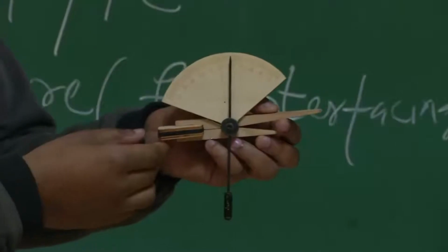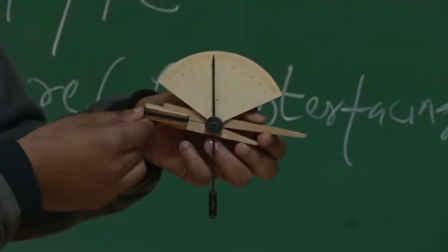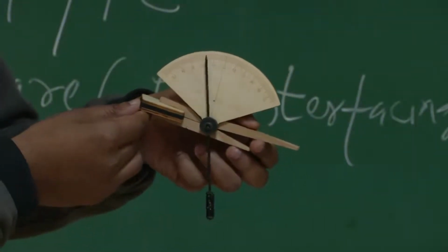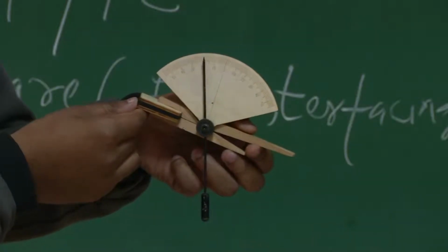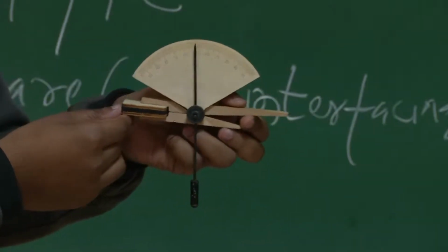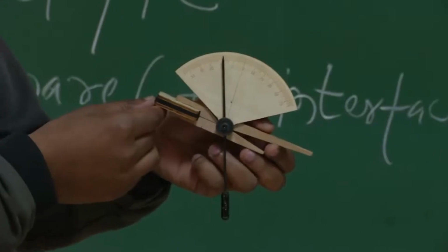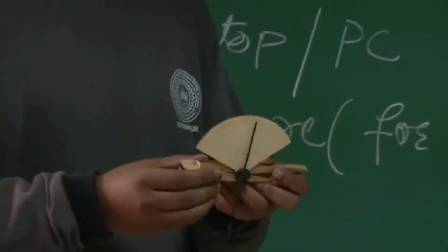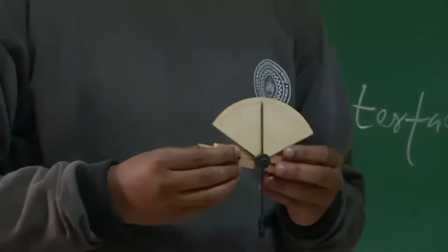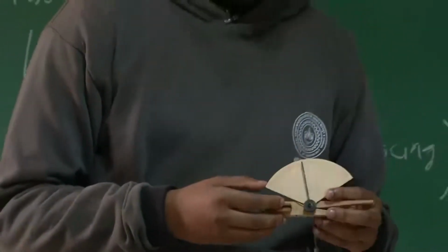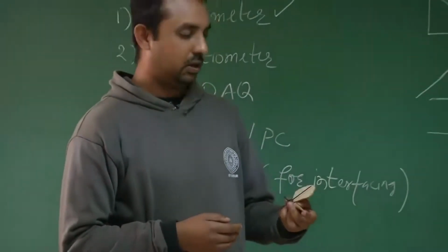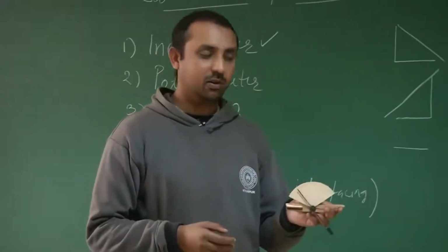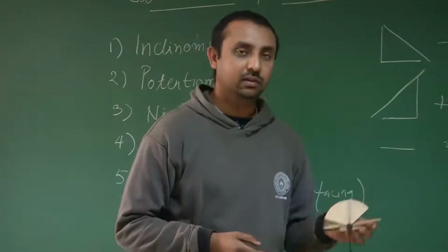As you can see, while tilting this instrument, the needle indicates what particular angle it has been tilted. This represents your inclination or positive or negative slope. Now, as you know, this is analog device, so the accuracy is not as high as that of a digital inclinometer, but earlier days this was used for determining your angle or slope.